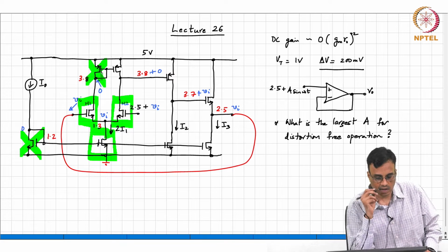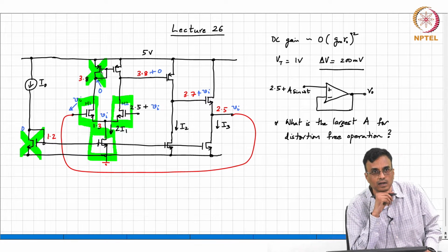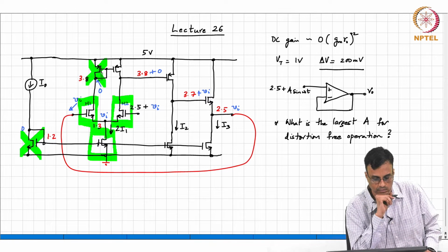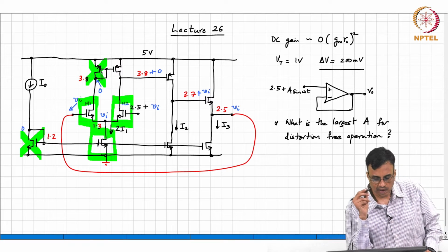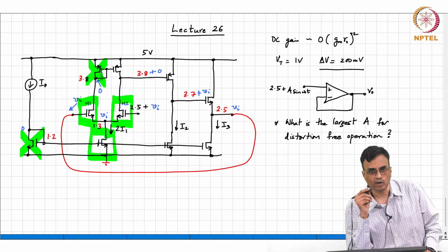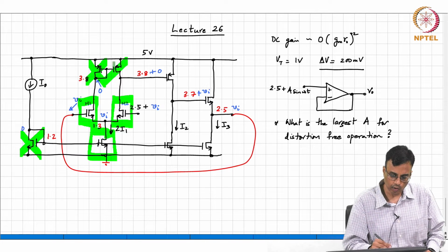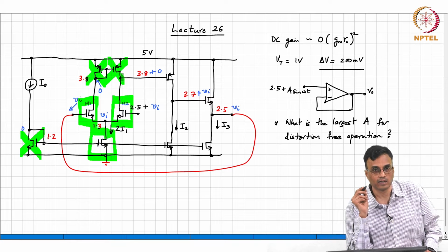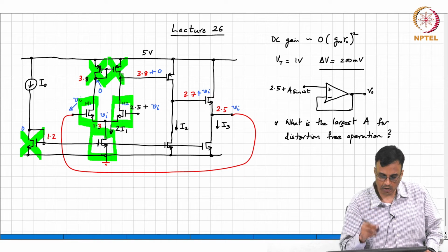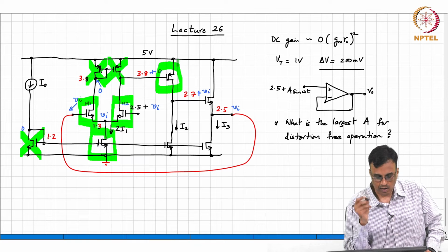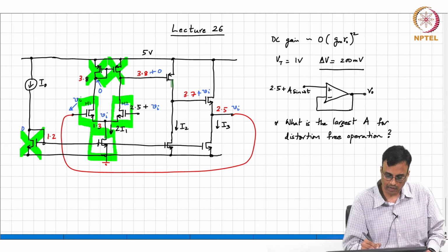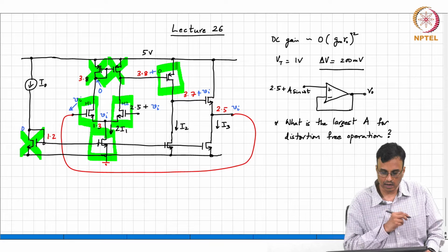What about the other transistor on the right? The incremental voltage at the drain is 0, so basically VDS is not changing. Incremental current is 0, current is not changing. Therefore, we don't have to worry about this as far as swing limits are concerned, right? Okay, what about the next transistor, this guy? The drain is swinging, so we basically need to worry about that chap.